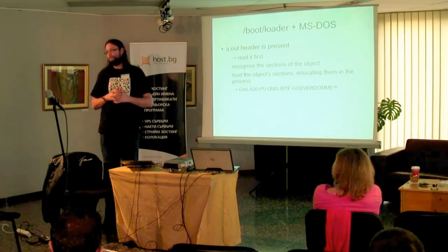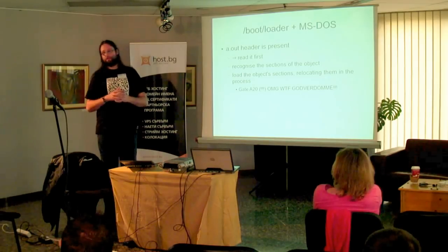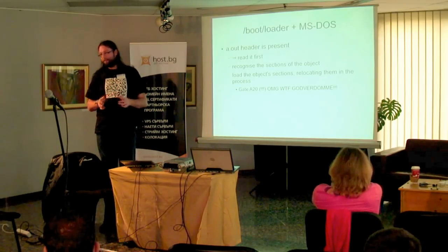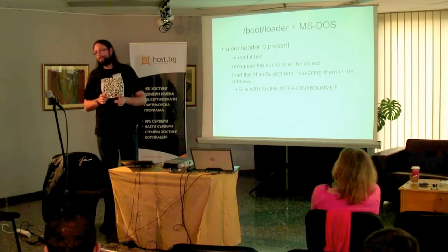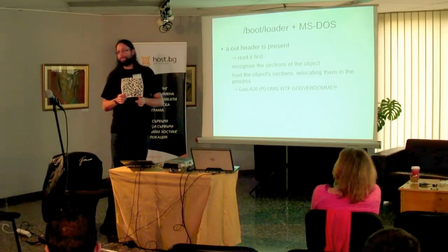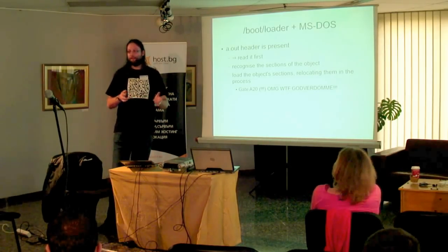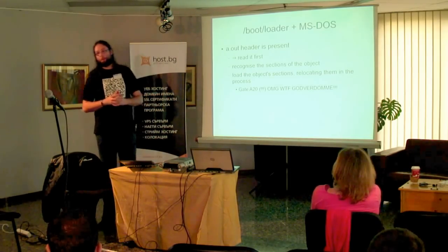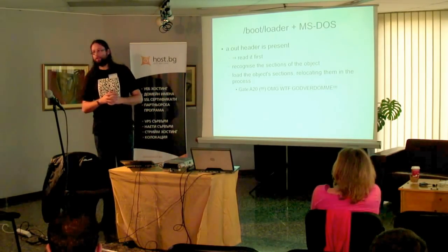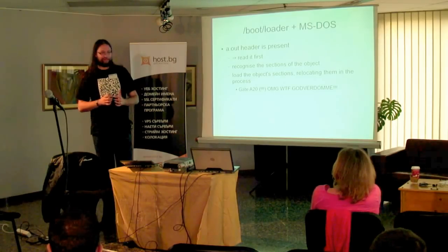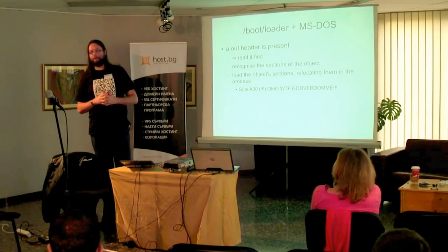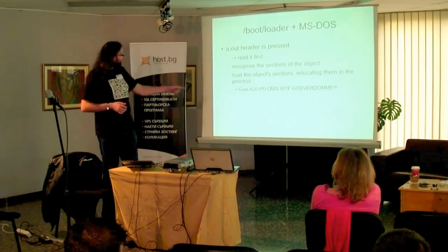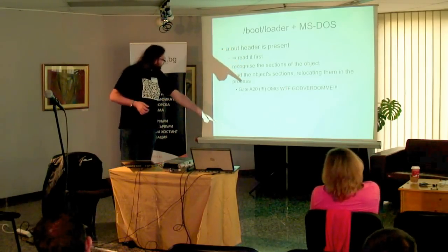How it's done? Very easy. You have to reprogram your keyboard controller. Long time ago, they did not have a lot of hardware in there on the main board, so they decided that they can use the keyboard hardware just to enable the gate A20.